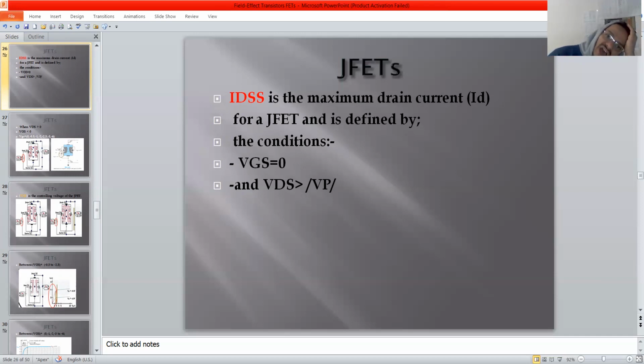And we will have a change at the upper points. The depletion region will increase to try to touch each other. Here, when we have a reverse bias voltage equal to -1, the depletion region will grow more, and the drain source voltage will be constant, bigger than 0. The current starts to flow from ID to IS like that, and electrons start to flow from down to up like that.